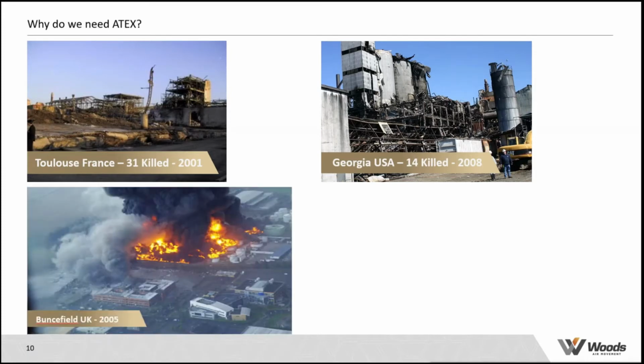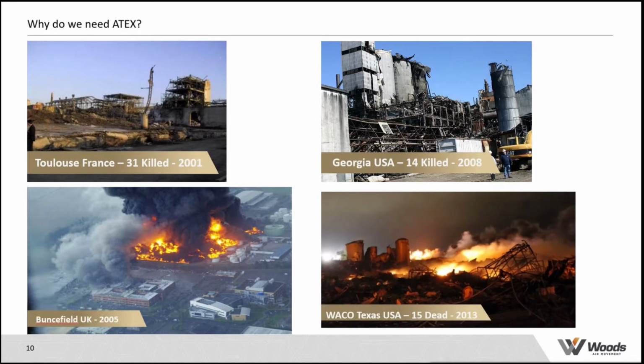It's an oil storage area in Buncefield in the UK. Amazingly, nobody was killed, but one of the reasons put forward was that a lorry tanker driver spotted a leak and went to switch off the pump in his truck, but that switch wasn't ATEX rated. So there was a spark with the fumes and that went away. And then one of the more recent ones, another 15 dead in another fertilizer factory. Fertilizer, unfortunately, is quite often the base of different explosive environments.